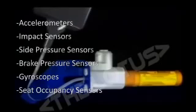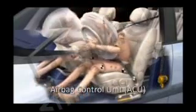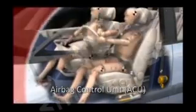Airbags. The first stage of the airbag deployment is the accident itself. The collision activates an array of sensors in the vehicle, including accelerometers, impact sensors, side pressure sensors, brake pressure sensors, gyroscopes and seat occupancy sensors. All these sensors are in intimate connection with the ACU, Airbag Control Unit, the very brain of the airbag system. The unit decides if and how to deploy the airbags. When the ACU detects that the deployment threshold has been reached, it initiates the inflation stage.